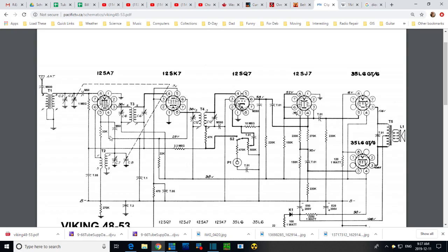And the alignment may be required to align these three things up. Now I have a military radio. It has 2 tubes before the mixer and 2 tuned stages before the mixer. And that results in an extremely sharp response curve. And that means the accidental sensitivity to, quote, image signals that might be occurring is greatly reduced.